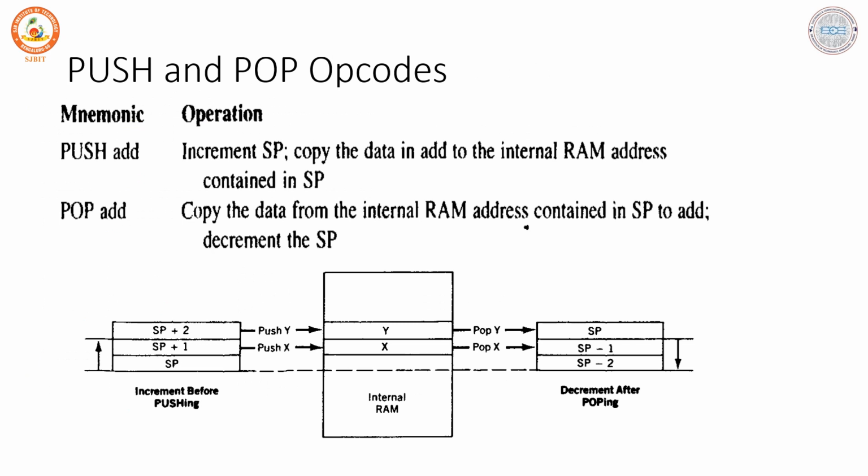We are going to discuss the instructions that are used for stack memory operations, and those stack operations are performed using push and pop opcodes. The push and pop instructions use the direct addressing method in order to move data between the direct address and the stack memory. And the stack memory we are talking about is a part of the internal